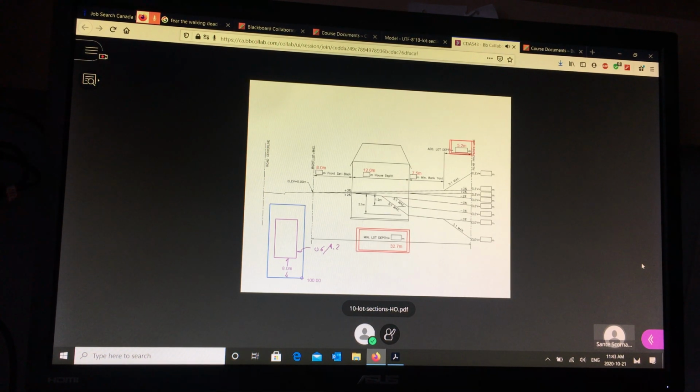If I want to know the elevation of the corner of the building here, I need to do two things. I need to come up from the front and calculate the elevation opposite that point on the lot line. Let's assume that's going to be 5%, the maximum allowed. So if the elevation here is 100, what's the elevation here going to be if we're going up at 5%? We want to drain down, so this is higher.